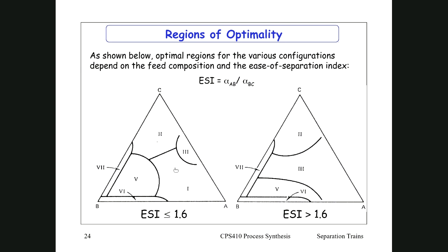So essentially, this is what I would expect you to do in the exams and tests: you can choose using heuristics. Let's say I do a 6-component system. You could use heuristics to choose the separations until eventually you land up with a 3-component system. And as soon as you have a 3-component system, the Tedder and Rudd method is going to give you a much better answer, because this method chooses the distillation column system based on economics.